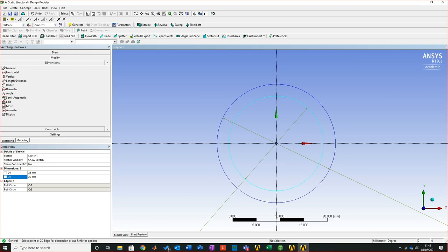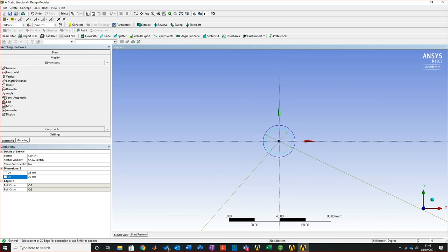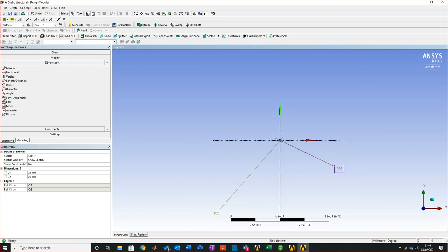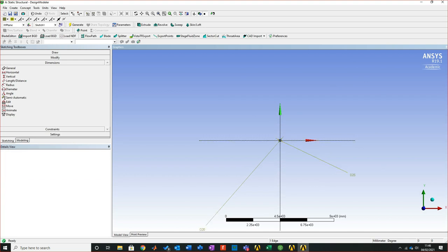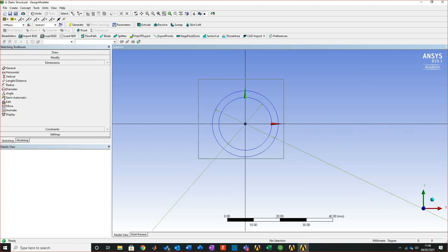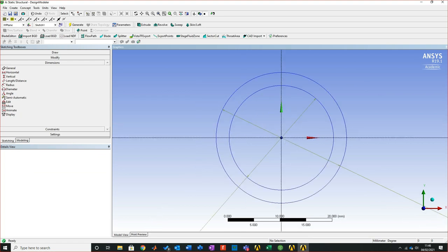Another thing that's annoying, which you'll just have to get used to. If I scroll this back out, you look at it, you see how I'm trying to make, you go, what? Right. You cannot move the diameters unless you actually modify the dimension. It's a real pain in the backside, but for what we want to do, we just want to make sure the dimension's right. We're not producing drawings from this. This is just going to give us the all-important piece of geometry that we need.